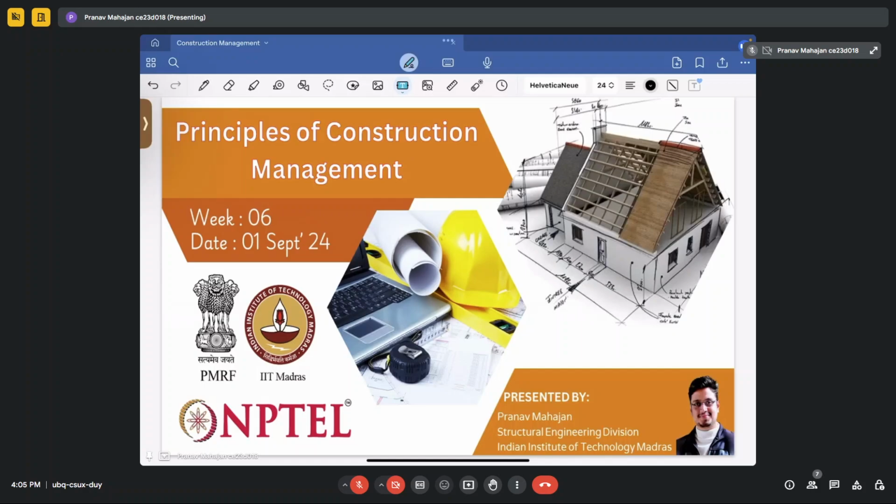Based upon the amount of resources available and the time leveling that is required, we crash various activities of the project on the critical path so that the cost of the project is brought to an optimum level and the total duration of the project is decreased.